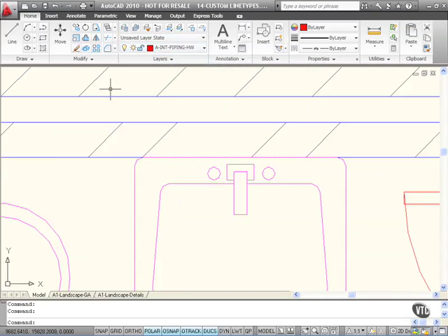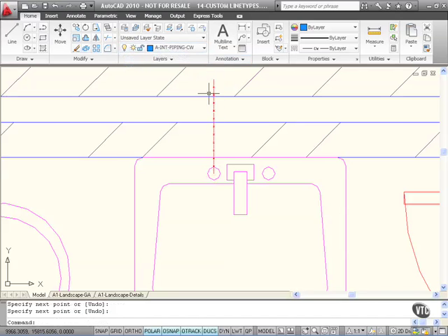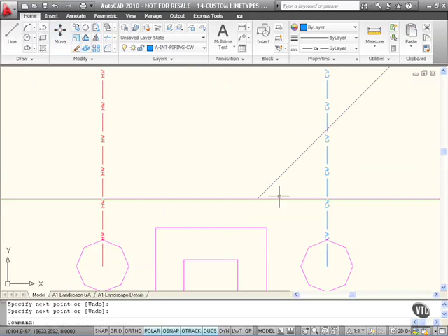There's the hot tap there, and I can place a line now from the center of that tap using my hot water. So I'll just press enter there. There's one line. I'll then go here to find the next one, my CW there. Again, I'll do a line from the center line of that tap there, coming into there. Let's line it in using object snap tracking. And there's my cold water as well. And if I zoom in now, look, I've got CW and I've got HW there. Hot water, cold water, due to my custom line type files.